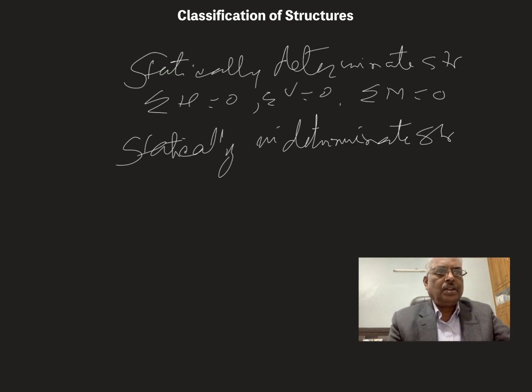are under the category of displacement methods. The force method is also called the compatibility method. In this method, redundant forces are taken as unknown, and additional equations are provided by the compatibility of the geometry of the structure under the applied loads.